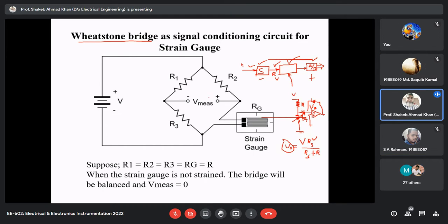Here you see the bridge is used in deflection mode, and that too in voltage sensitive mode. Deflection mode is also of two kinds, current sensitive and voltage sensitive. So here it is used in the voltage sensitive. Voltage sensitive means your detector is voltage sensitive. Voltage sensitive detectors have very high input resistance. So here it is open, so it is like your voltage sensitive.